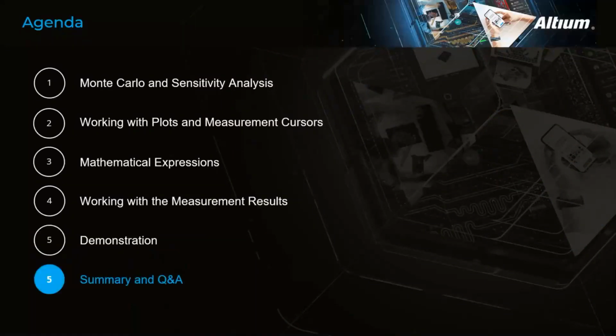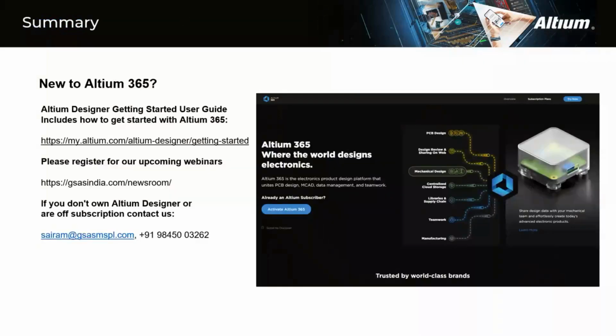Yes, now to the summary. To summarize, we have discussed the different measurement results, the Monte Carlo analysis, and the sensitivity analysis. We have discussed how we can work with the plots and measurement cursors, followed by mathematical expressions, and also how we can save the waveform and how we can use this saved waveform as input to your circuit.